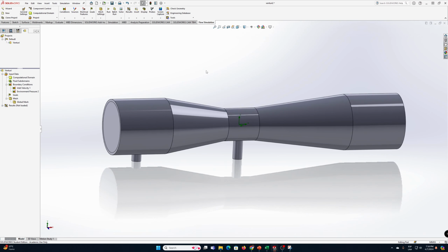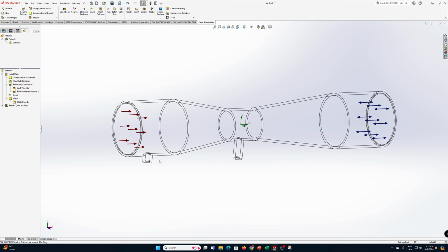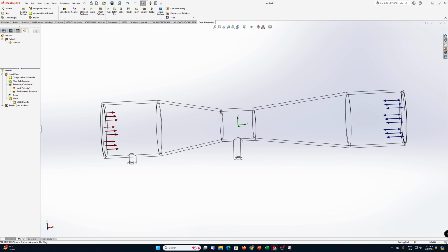Now, before we continue, we can verify the preview of the boundary conditions. The only thing we need to do is go here to the top in the display option, go into display, and select the option that is transparency. With transparency, we will set the value of the transparency in the solid. So if you put it like 0, it will be completely opaque. And if you put it almost to 1 or 1, it will be completely transparent. So now, for example, we put it like 1, and we have the representation of the boundary.